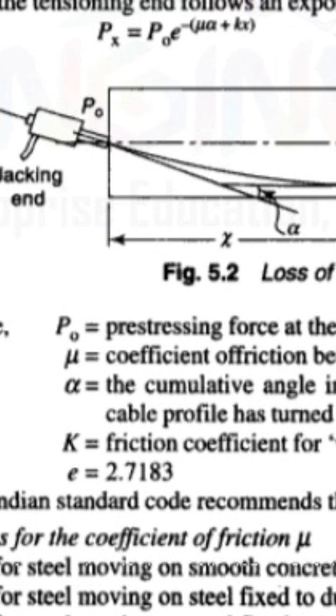The friction loss can also be reduced by several methods, such as over tensioning the tendons by an amount equal to the maximum friction loss. Another method is jacking the tendons from both ends of the beam. Generally this is adopted when the tendons are very long, or when the angles of bending are very large. In these cases the friction loss can be reduced.